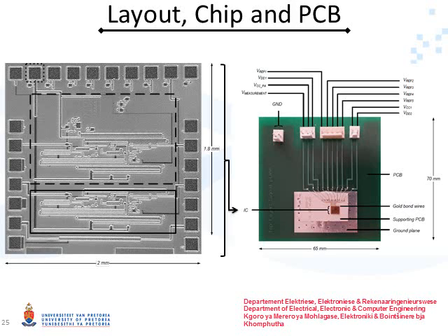Wire bonding was done on the DC bond pads. The wire bonding process required that all the DC bond pads be located in one line, either on top or bottom of the die area. Otherwise, the wire bonds might touch, and connecting it to the PCB contact would have been difficult. The DC bond pads took the maximum available space, and no additional space was available in a single line format for additional DC bond pads.